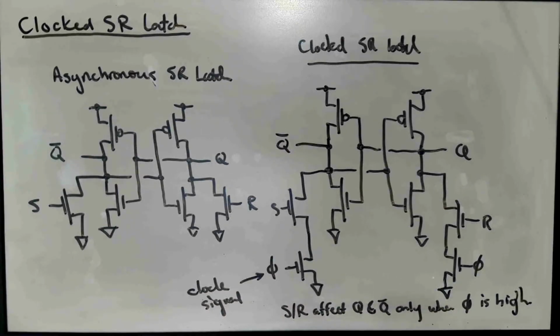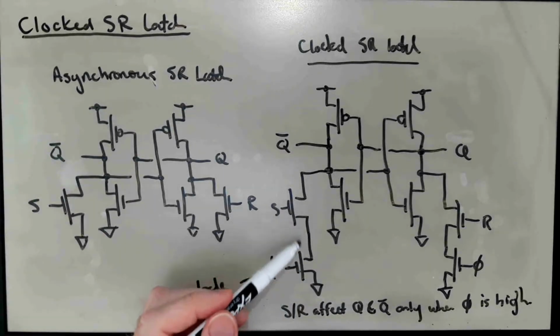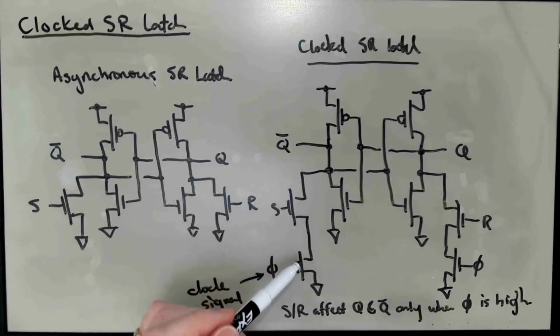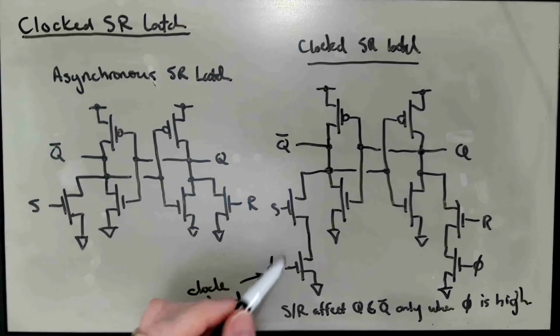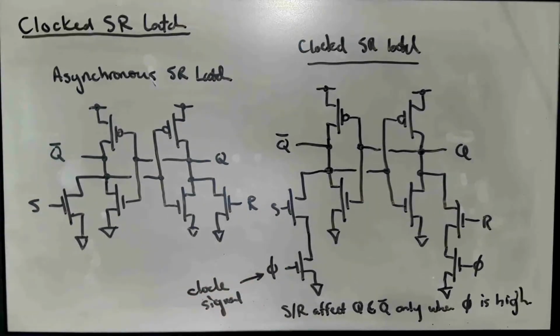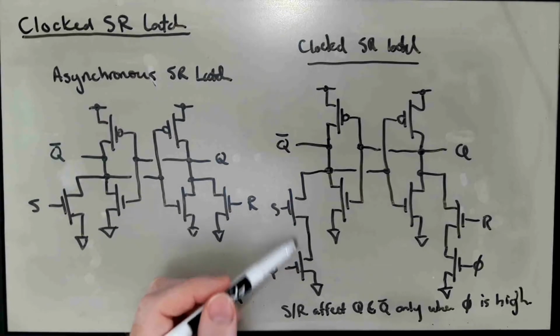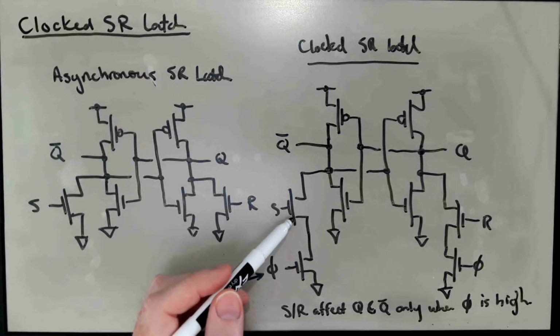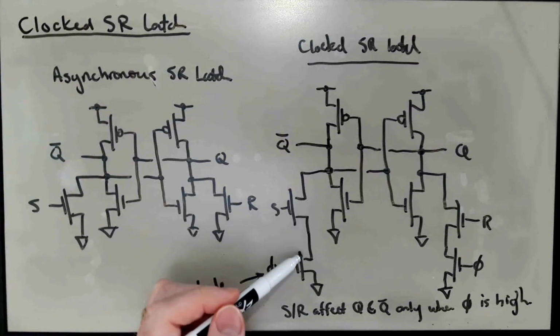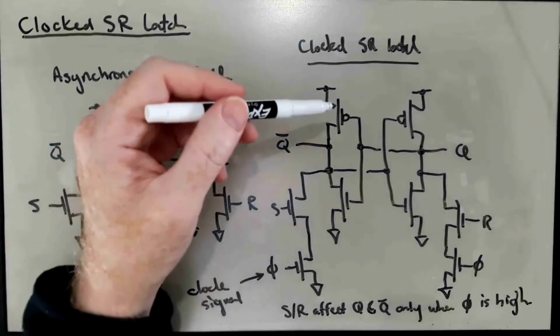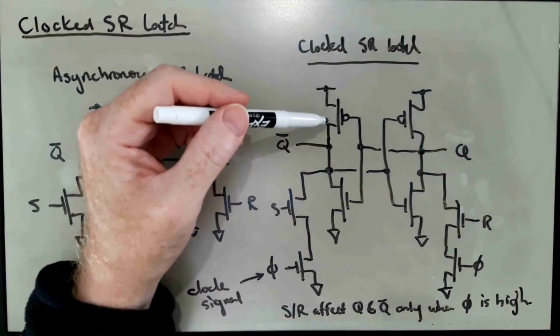Okay, now this has the problem of basically weakening the access device, right? When we have two transistors in series, as you'll see in the pre-lab for lab 6, if these two gates are both at 5 volts, it's almost like we have a transistor that is twice as long as either one of these, which has half of the strength ratio. And so by putting another transistor in series with our access device, we're basically exacerbating the writability problem.